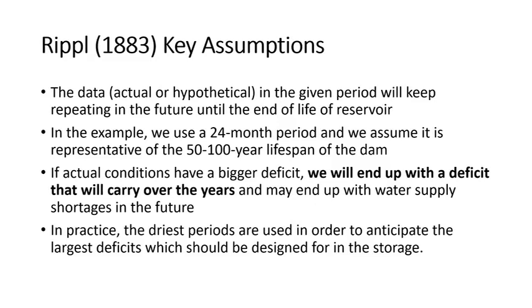If you underestimate the deficit of the dam, of course this will carry over years and years and years, and you will be in trouble in the long term. So in practice, the driest periods are used in order to anticipate the largest deficits, which should be designed for in the storage.